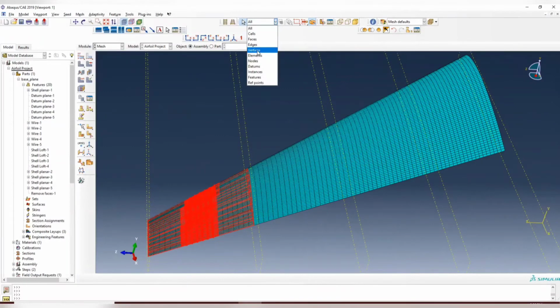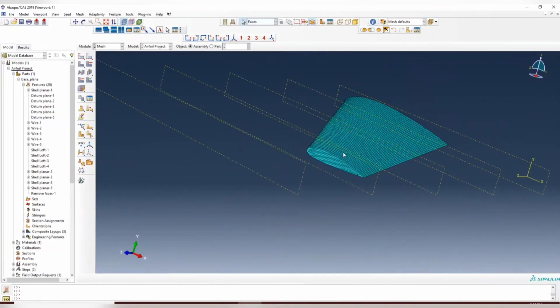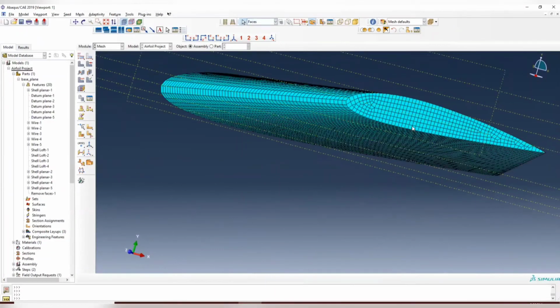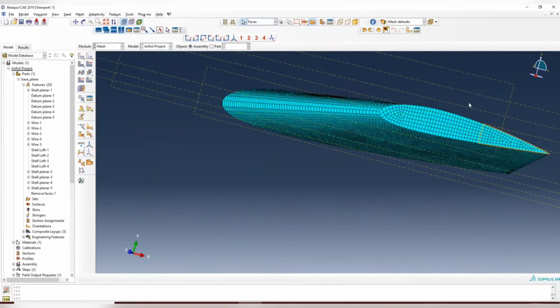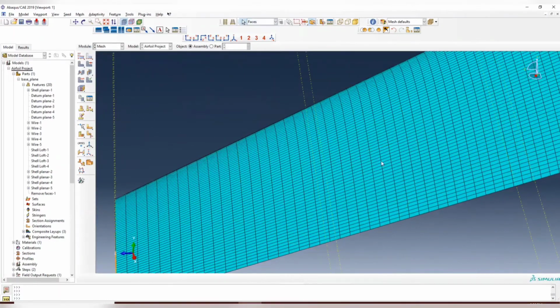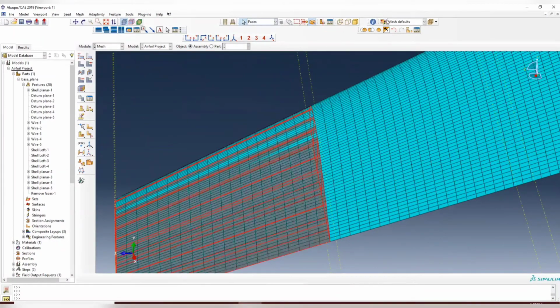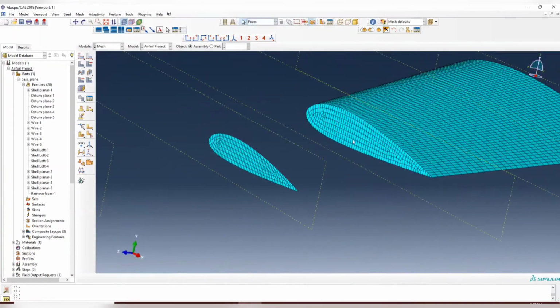We can select the faces, select all the faces here and hide them. Inside the spar, you should see these two meshed relatively well, and these two may have some triangular form, but it doesn't matter that much. Double check all of that. It should look good.